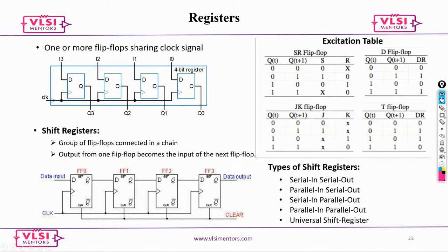But before that, let me just quickly give you. So you have different flip flops in the textbook that you would have gone through. Say SR flop, and then you have a JK flop, and then you have something called D flop, and then you have something called T flop. Now if you look at industry, we only use DFF.